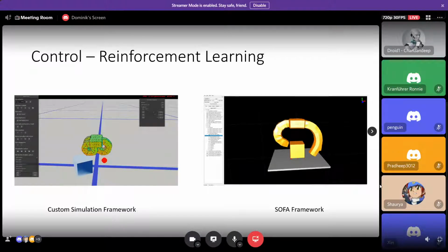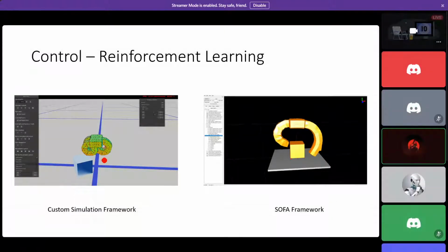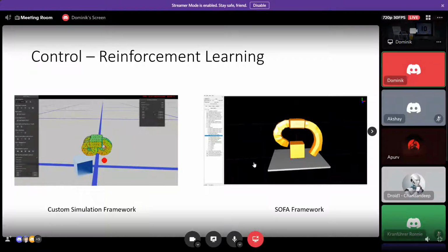I have a question. I am Apoorv. Did you mathematically model slip? Did you incorporate any kind of slip in your model? No, you're estimating only the contact forces. Yes. Again, that's a very simple approximation. I think the goal for us is to really have something that runs as fast as possible, so we can do learning. For us, we don't care too much about slip in that case, because as I showed in the beginning, stable, robust grasps or stable manipulations aren't the big issue for soft robots. Of course we would love to be able to model that, but I think that's not the main priority for us.